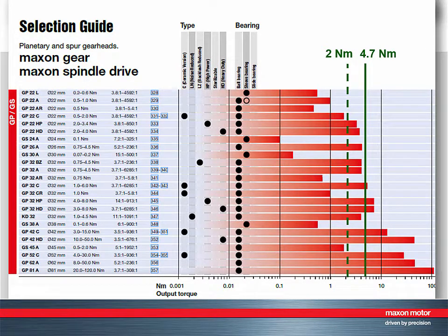The maximum intermittent torque of the gearhead is about 50% higher than the continuous one. The required peak torque is relatively large here. However, the GP26A, for instance, is one of the gearhead types matching also these requirements.